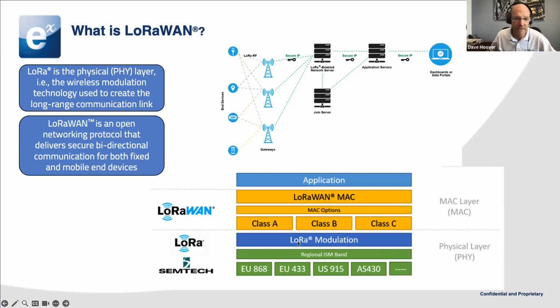On top of that is built the LoRa modulation. Again, when you hear just LoRa, that's speaking of the modulation in the physical scheme. And then on top of that, in the yellow here, you have LoRaWAN, the MAC layers and above, and the different classes of communication, which refer to whether the device can just talk and listen, things like that.